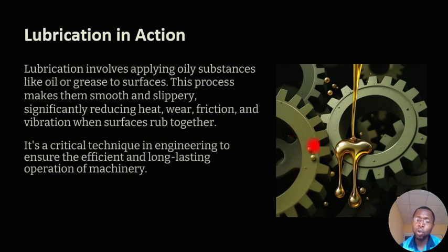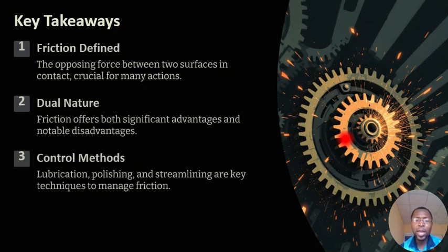And with the reduction of friction, you also reduce noise. Imagine if there is no oil here, and the teeth of the gears are hitting each other. You'll be hearing the noise, the kind of clunky noise. But with the presence of this oil, it will reduce that noise, which is a result of the reduction of friction.